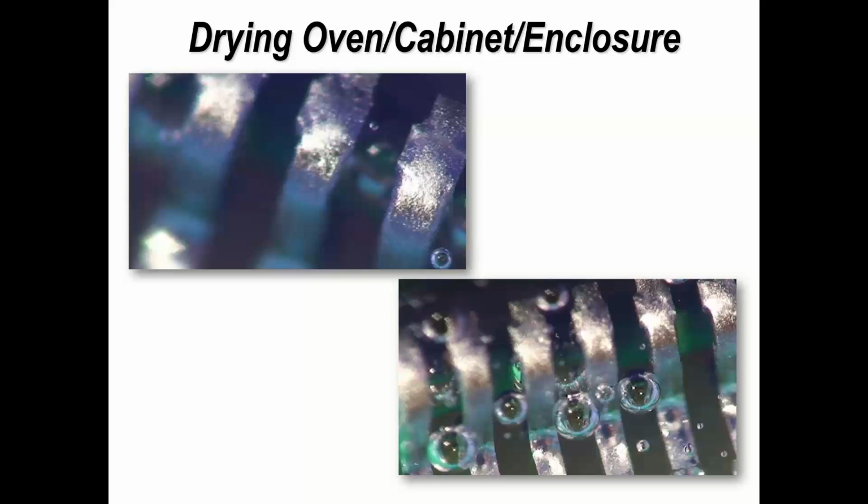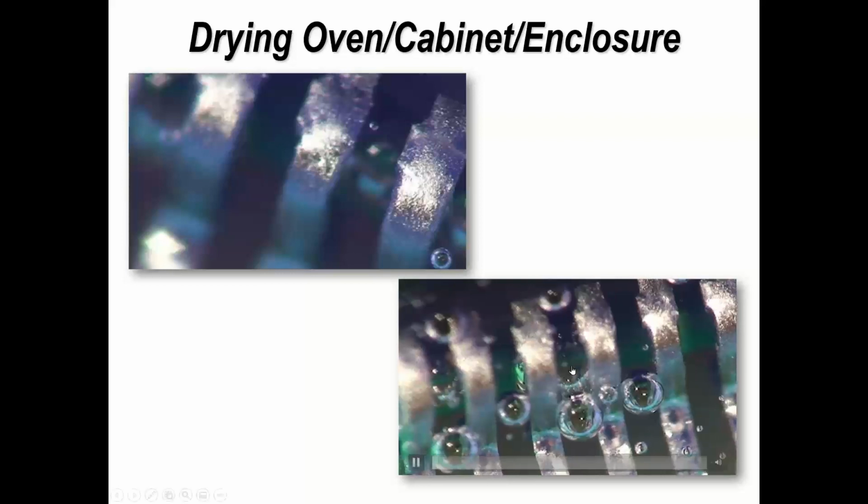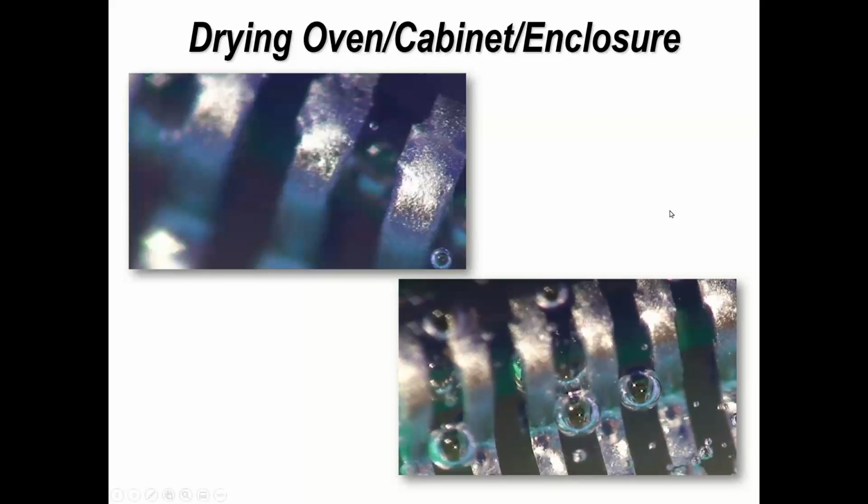But if you were to put on one coating and then another coating, or put on a very thick coating, it takes longer for those bubbles to escape. You can also get outgassing from surfaces like board materials. If the board material doesn't wet with coating, it's non-wettable, then you'll tend to find bubbles or separation of the coating on the surface. There are lots of other reasons, but I just highlighted a couple.